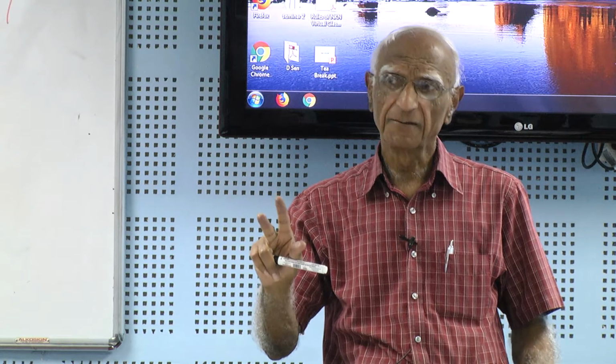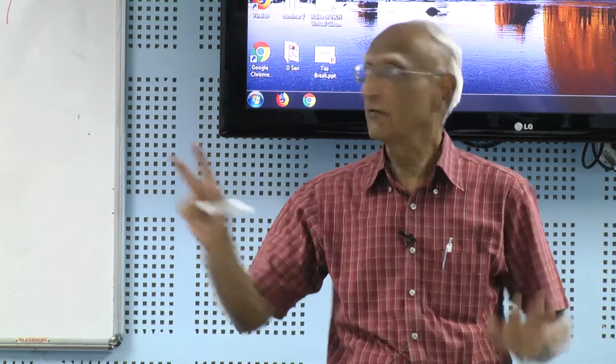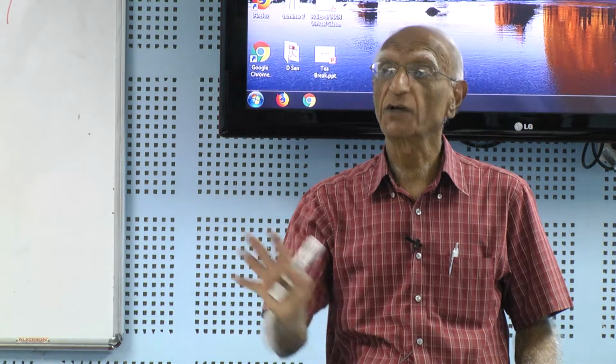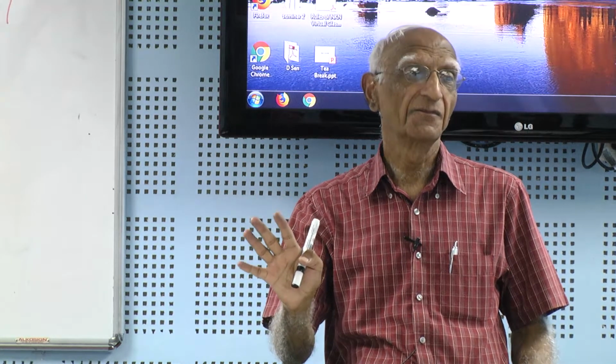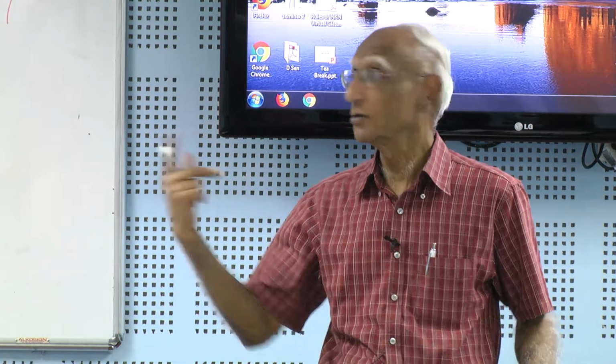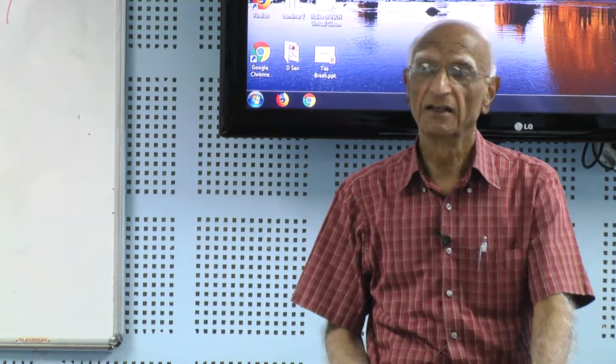Because if you look at Fung's book, Y.C. Fung, he gives you stored energy functions, which are our phis here now, except temperature is kept constant. They are exponential form. But he is giving you for isotropic materials, which we have not talked about yet. It will come, because you asked me to do anisotropic first.